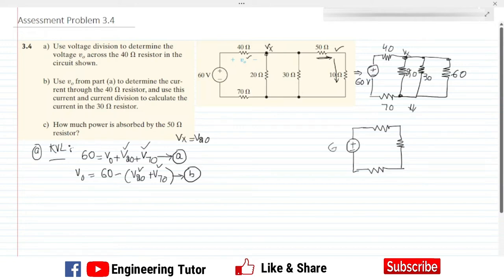We are actually simplifying our circuit to find out the unknown quantities. This is 40, this is 70, and this is again 20. So now we can see that these two resistors are in parallel. 30 is in parallel with 60. So when we calculate their equivalent, this is a 20, and 30 and 60 are in parallel, and their equivalent will also be parallel with 20 ohm, and when we find it, we will get 20 ohm here as well. So simplifying again, we will get these two are again in parallel.